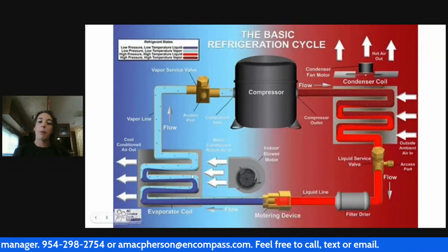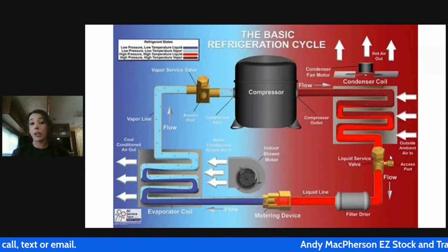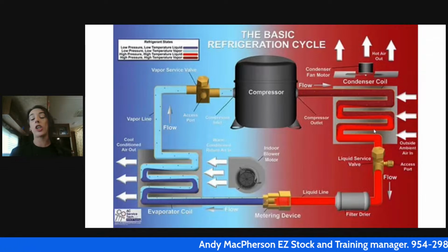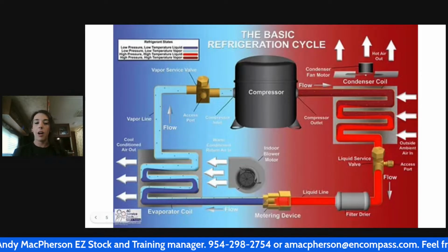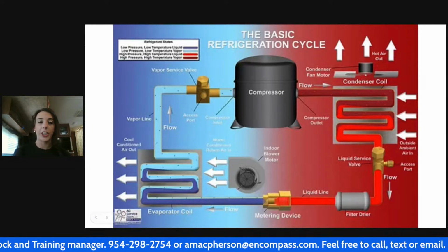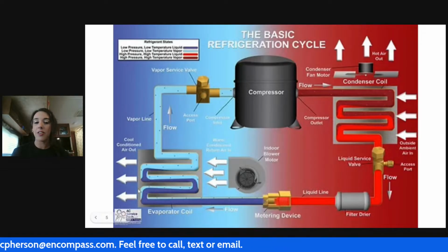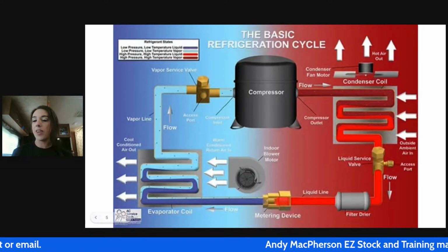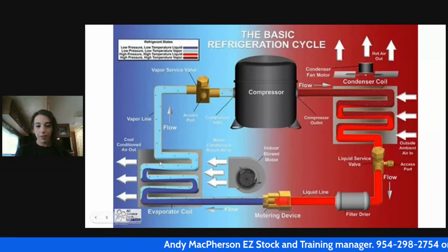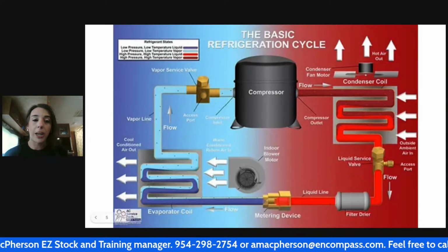In that evaporator, it's doing the exact equal and opposite job of the condenser. So where we were providing a lot of surface area over here, as much surface area as possible to allow phase change to occur naturally, we're doing the exact same thing over here in the evaporator coil. It's just the opposite. So where we were changing to liquid, now we're changing to vapor. So on a perfect system, again, about here, we're getting saturated as a vapor, and then we're traveling through all those coils, and we're taking the surface area from the fins, and we're transferring that heat again to change phase. Now, as we come out and exit the evaporator, we are a low pressure, low temperature vapor.